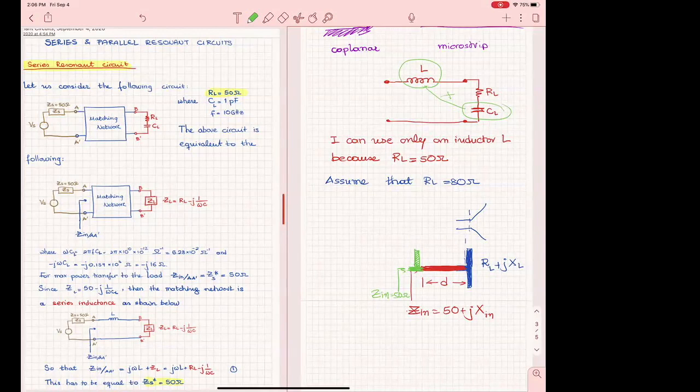I mean, if you have a transmission line and a stub, you can either put the stub next to the load and then the line, or the line next to the load and then the stub. And in this particular case, it does not make sense to put the stub next to the load because that has an antenna in there. There will be other cases where it may make sense because instead of an antenna, you may have just another section of a transmission line that is connecting you to another circuit, all right?